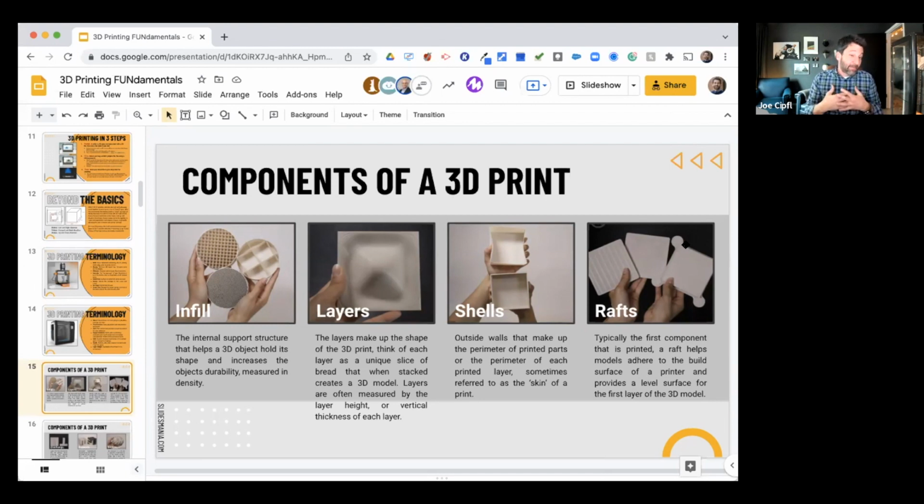The 3D printers that I'm going to recommend to you today all auto level, so that's one headache that you don't have to worry about. But sometimes 3D printers can be tricky with their leveling. And so rafts can sometimes help if you have a 3D printer that does have some leveling issues, to help that 3D printed object stick down, adhere to the print bed better.